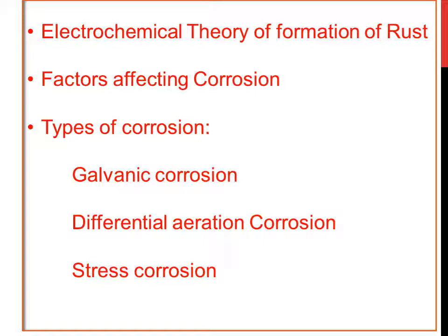And also we have discussed the nature of the corrosion product and how it will influence the rate of corrosion. So once the corrosion process is initiated, the product formed influences the rate of corrosion. If the product formed is highly stable, or insoluble, or uniform throughout the surface of the metal, then it acts as a protective layer on the metal surface and it will prevent the corrosion